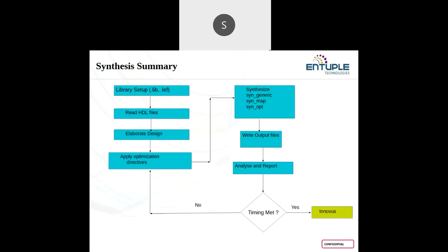So any further queries? Ma'am, what is path histogram? Sorry? What is path histogram? See, if you go to the timing debugger window, we have the options to see the timing paths, whatever timing report I am generating. For that timing report, I have the option to see the histogram. The same way, we have the option to see the histogram in the timing debugger window.